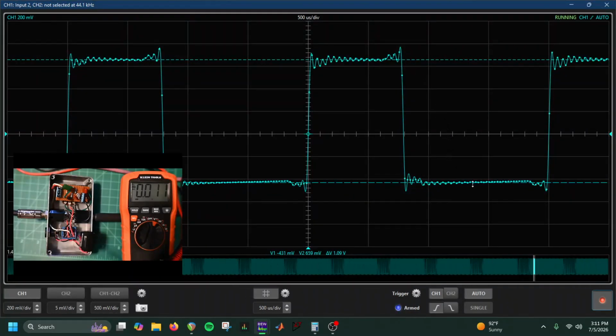And on the negative side here, you can see a similar behavior. You get all this clipping. You don't get the nice sinusoidal curvature. The thing that's interesting here is this one at the positive is 660 millivolts, and this is 430 millivolts. So there's actually this asymmetric gain that happens between the positive swing and the negative swing. So that's what we call rectification.